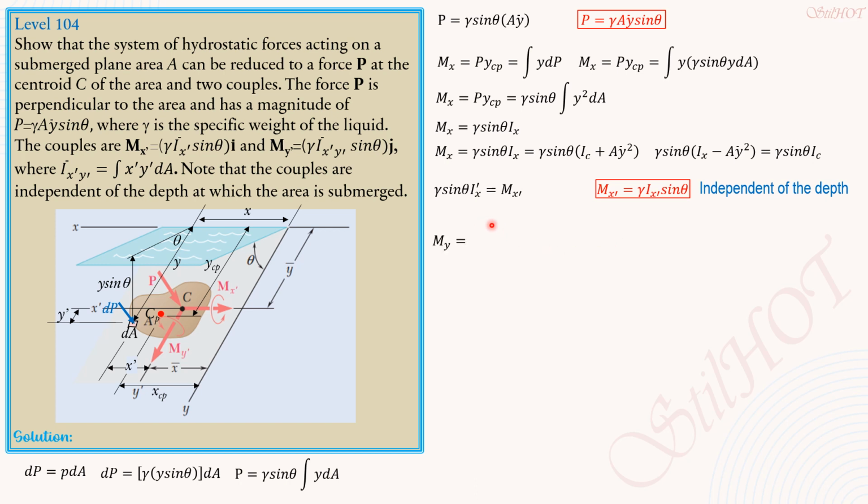So likewise, My equals P times x sub cp, equals the integral of x dP, because the distance of the differential area from the y-axis is simply x.